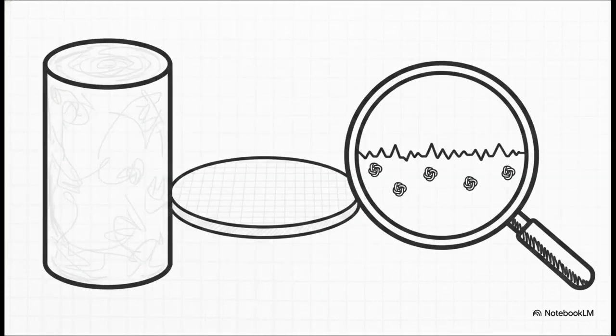The trouble actually starts incredibly early. Even during the initial silicon crystal growth, you risk oxygen contamination or crystal dislocations that just totally disturb the regular atomic arrangement of the silicon lattice. Then, when you move into wafer manufacturing, things like slicing, lapping, and chemical-mechanical polishing, those mechanical and chemical treatments introduce localized stress points. Even these impossibly tiny disruptions in the atomic structure act as leakage pads, and they severely weaken any subsequent thin film growth.